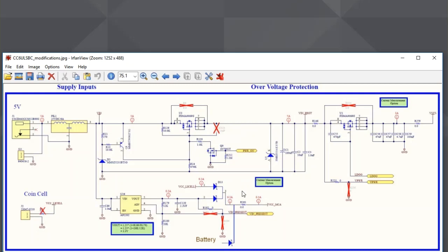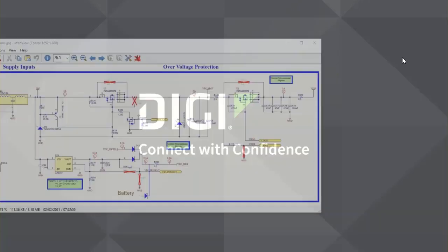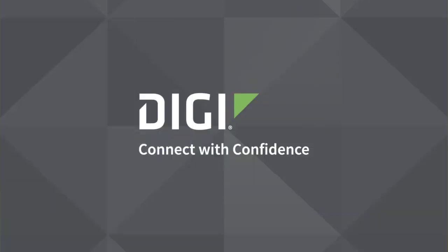And the second thing that we need to do is to connect the cathode of an external Schottky diode to this VCC MCA power rail, in order to be sure that once the mains has been completely removed, we will only provide energy from this power into the MCA. So let me show you how to do that on the real board.